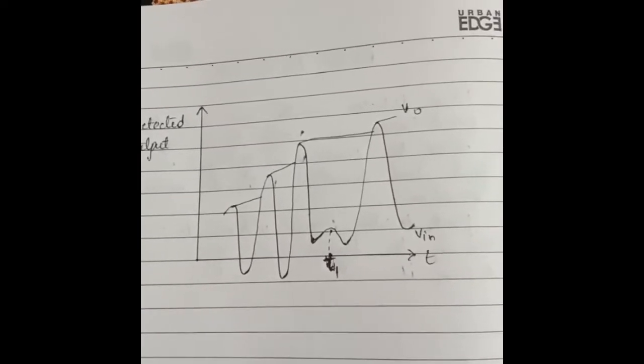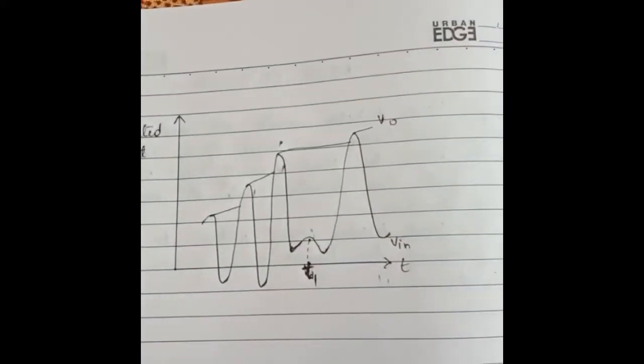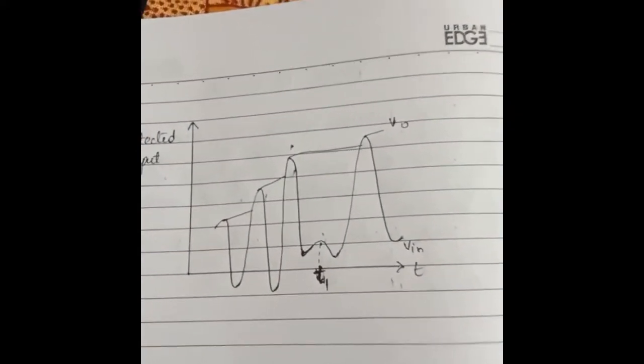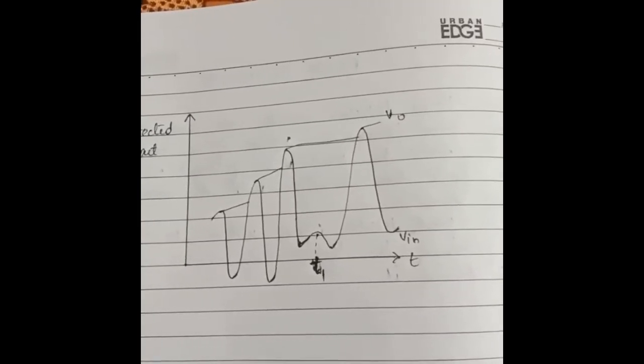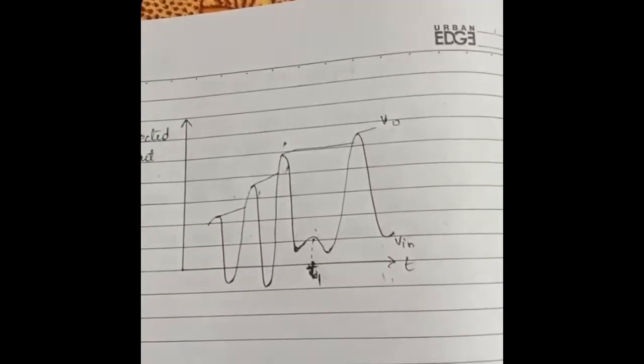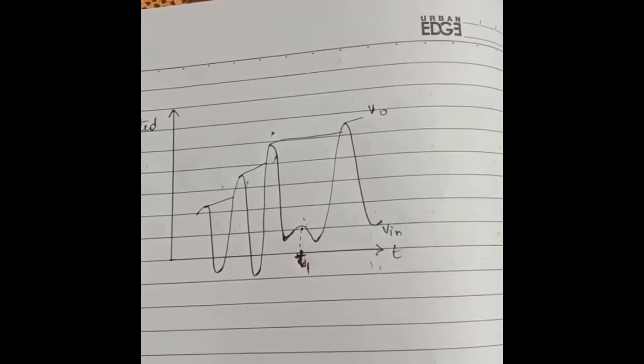As we can see in the waveform shown above, at time t1, the circuit misses the peak of the input signal as it is less than the previous peak of the input signal, thereby allowing the capacitor to hold the value of the previously occurred peak.